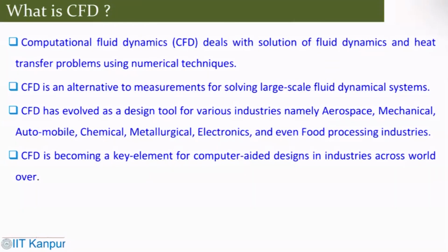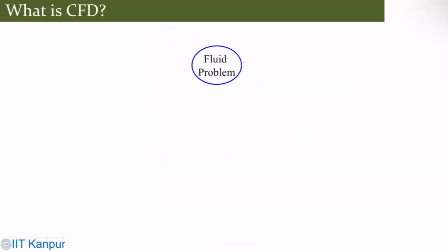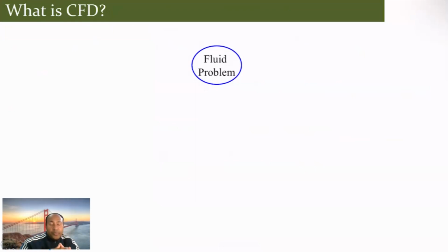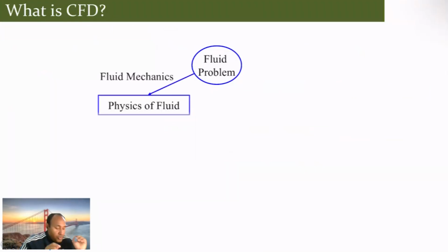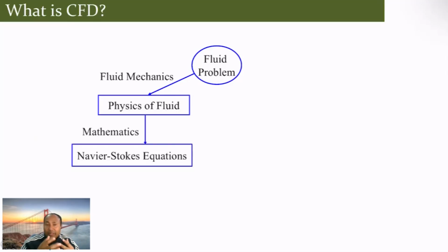Now, how does CFD work? When you have a fluid flow problem, the tool is going to give you a solution to a physical problem, which is a problem of fluid mechanics or heat transfer. So you understand that, and then you try to find the governing equations. Typically in fluid flow problems, things are defined by the Navier-Stokes equations.